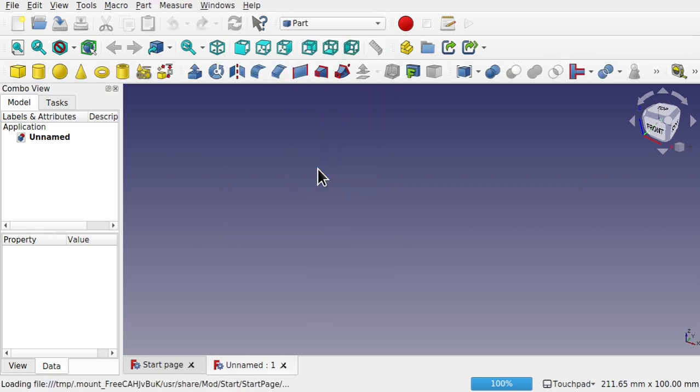So we're going to go into the Part workbench. This tool works with both solids, ruled surfaces, planes, etc. It doesn't matter which ones you use in there, what shape you use, you'll be able to blend a surface between them. When I say blend a surface, we'll actually create a surface between two edges of the selected planes or the selected objects, using those edges to connect the surface between them, and it will use the face that you selected to shape that surface.